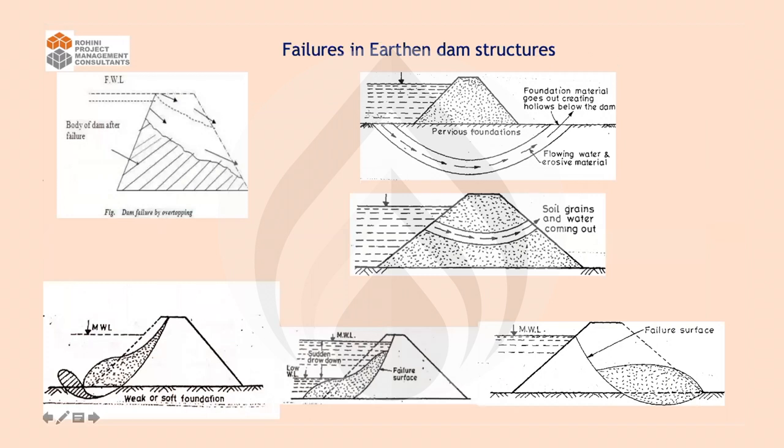Coming on to this, all this knowledge has to be put into lake structures or dam structures. Today we are going to talk about some failures, some failures on the earthen dam. You can see there are different types of failures which occur. The dam might fail because of overtopping. Again, why is it failing? Because of the full water level being there, the compaction not strong, the edge protection not given. Basically, you don't have the riprap there. So there might be many reasons. It will be customized, and the solution also has to be customized.